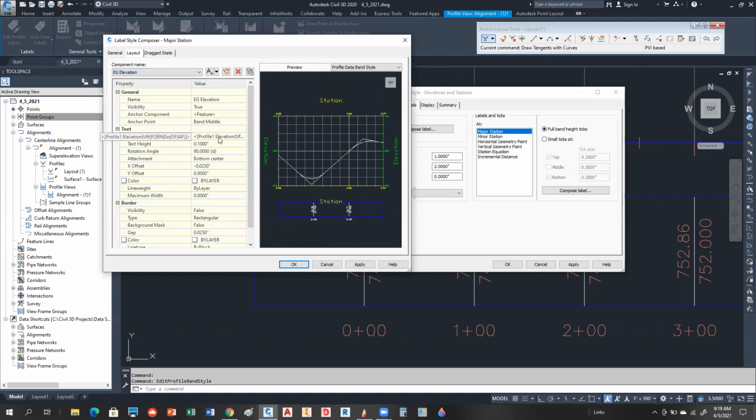And again, these are kind of typical heights and those kind of things that you've seen before. But one of the things we like to do in profiles is you don't normally show 2 decimal places for existing ground and 3 for proposed. Usually it's 1 decimal place for existing because that's plus or minus anyway, and 2 for proposed.